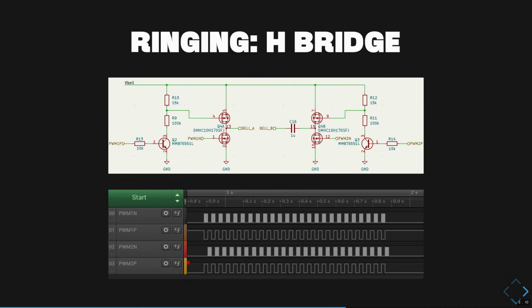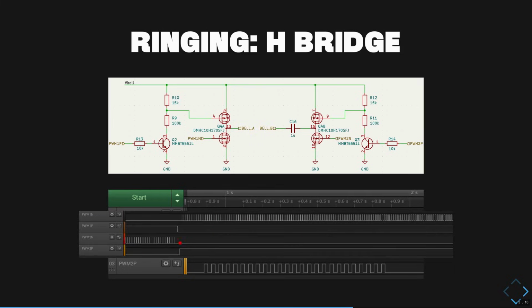So here that's traced from a logic analyzer, and you can see here this alternating between on and off states is still the same for the upper transistors, for the P transistors. But for the lower transistors, for the NMOS transistors to the bottom, I did something else. I feed in a higher frequency PWM signal with a duty cycle that is modulated by a sine half wave. So you can see it here. I hope it's visible well.